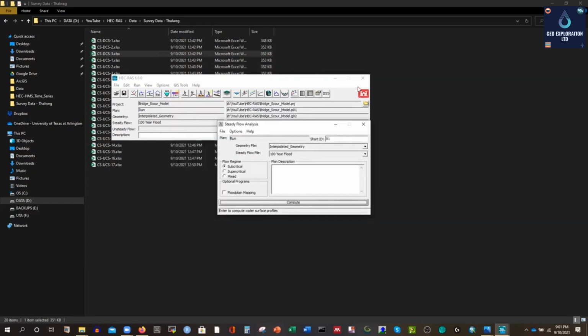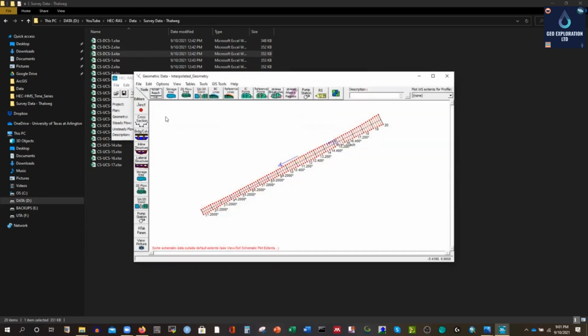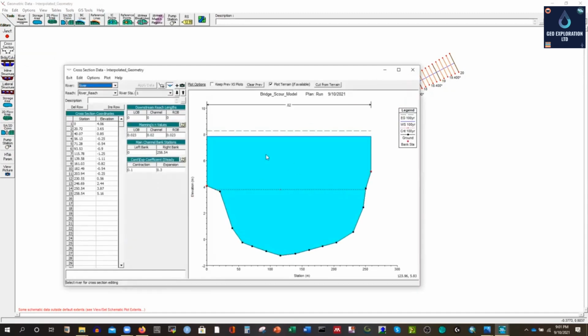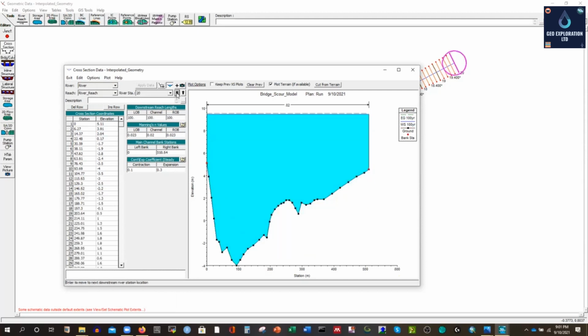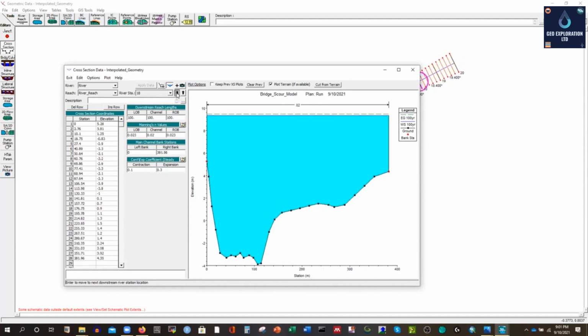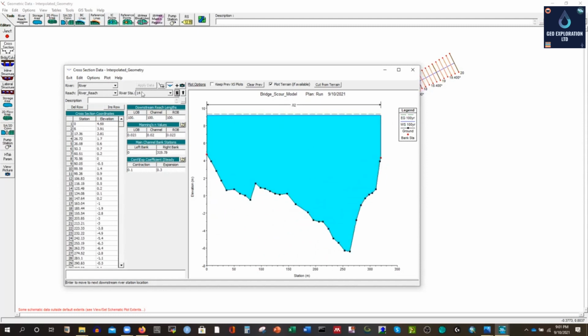We can see the result right now. I'm just closing that. See, if I open the geometry this time, and select the flow condition cross section, we'll see the water level, right? See, now the cross section is filled with water. This is the most downstream one, and if you click there, you can go upstream to the next cross section. Because we interpolated, it is just 19.8, and it is giving the IDs, and you can see we have this water, and you can see the velocity profile.